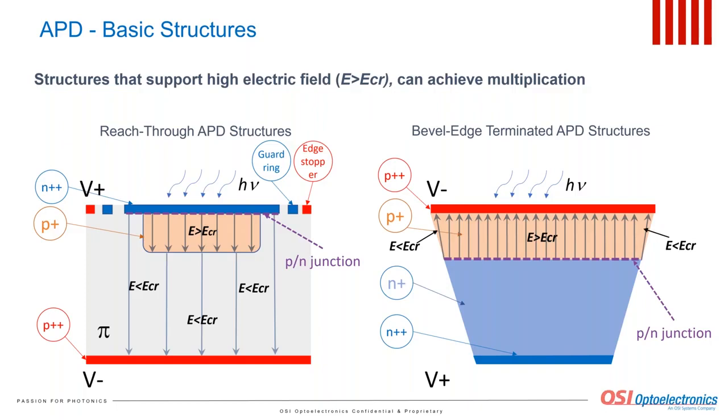As a result, the avalanche multiplication will proceed uniformly everywhere except the edges, and the dark current generated at the edges of the die will not participate in multiplication. Such an approach greatly improves the uniformity of the avalanche process.